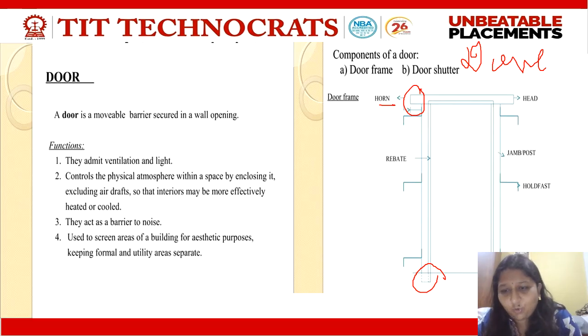Groove means basically a hole. Dove is nothing but the extended portion. As you must have used pens, the pen cap has a hole in it, so we can insert the projected pen-like portion into the cap. Similarly, this portion of the vertical post has an extended portion, and there is a hole here in the head of my door frame. The extended portion gets inserted and in this way the frame gets assembled.